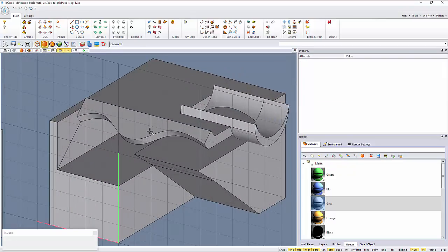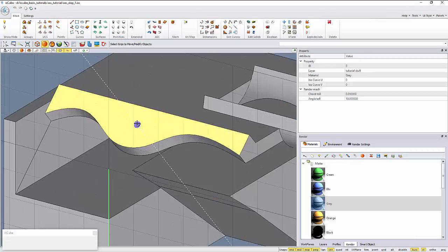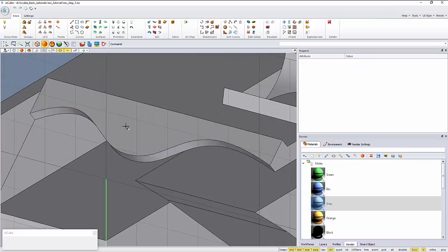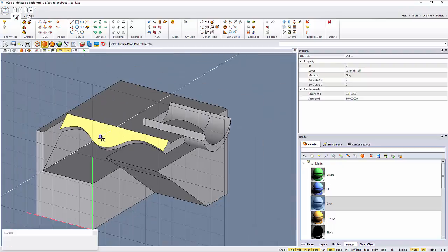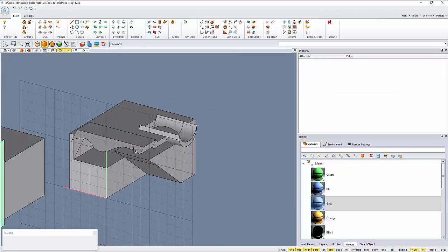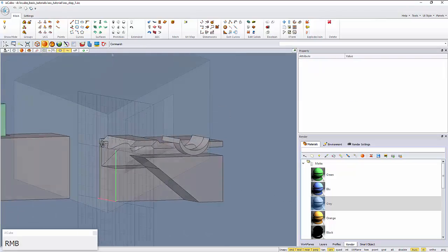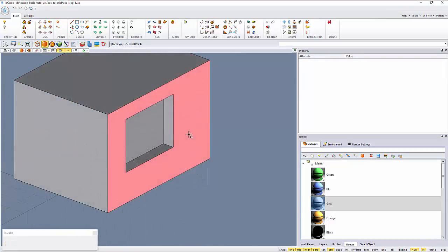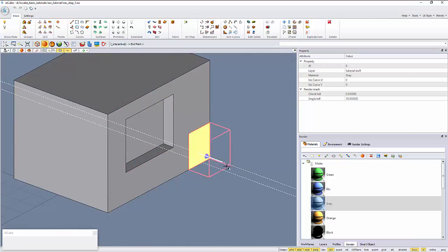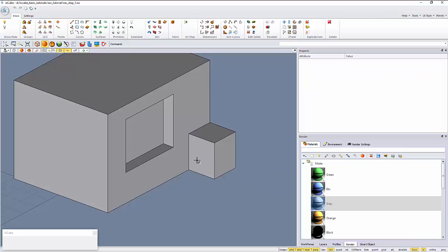So remember, single click, you push-pull in the direction of the face. Alternate click, you drag in the direction of the UCS normal like this. We can also start drawing here and drop out over the face. It would work in the same way.